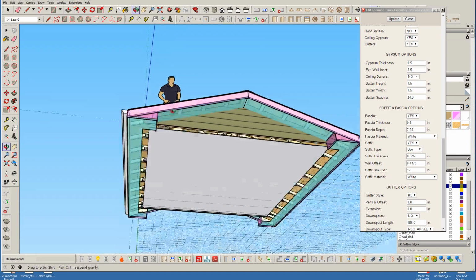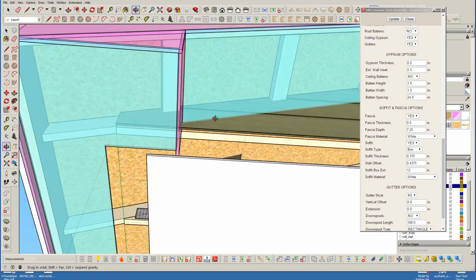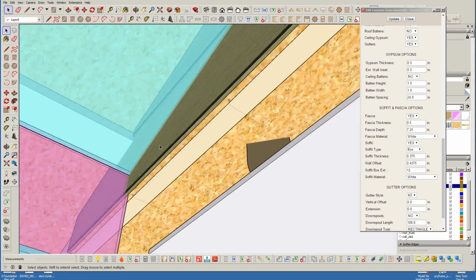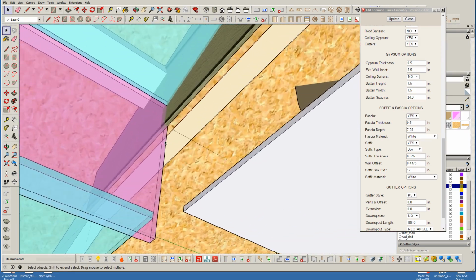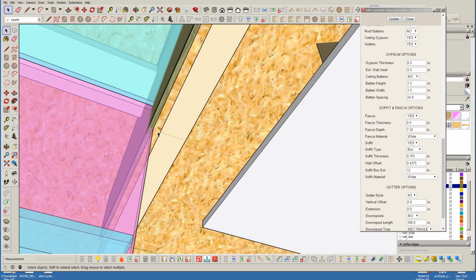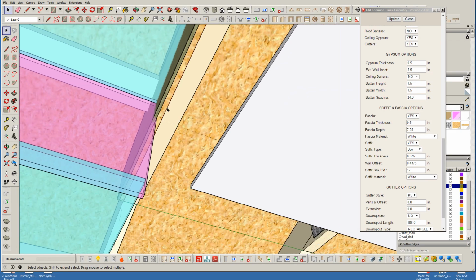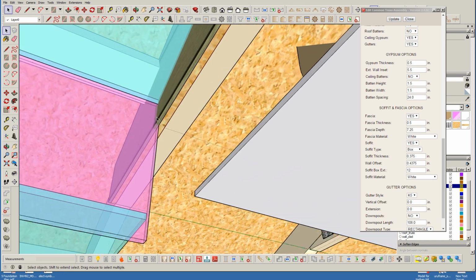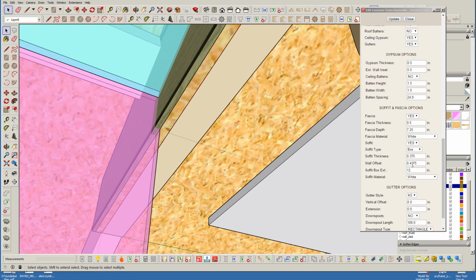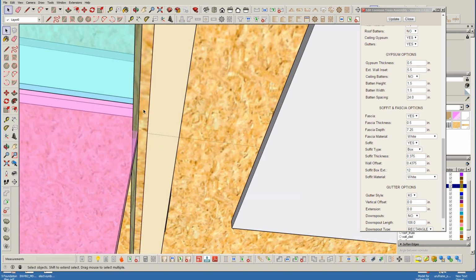And again, there's that little wall offset parameter. This actually demonstrates it quite well here. It pushes this up to your OSB. It doesn't bring it right to the framing. If you want to account for your cladding and everything, you can change that number up. I didn't try to make it work with this specifically, like if you have OSB, it's going to send it to there or there. I just left it open-ended for the user so they can adjust that.